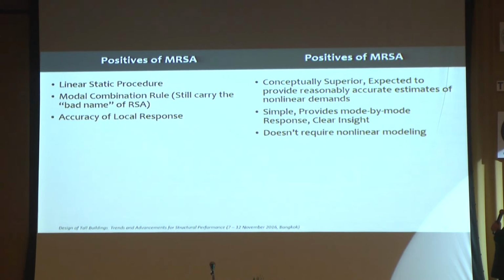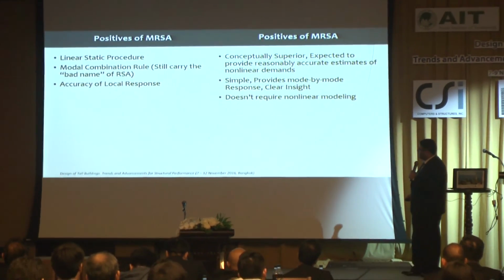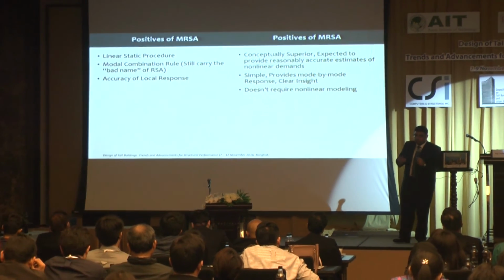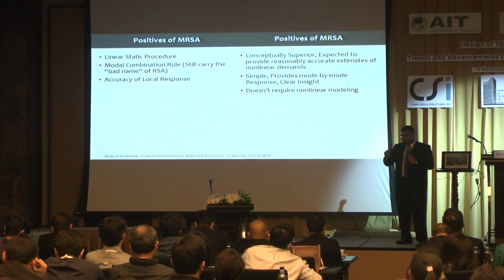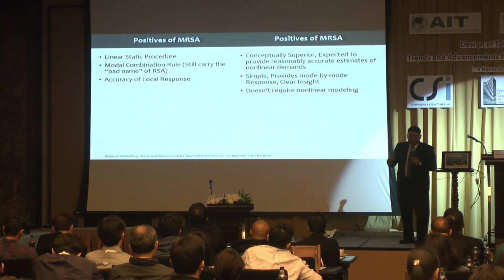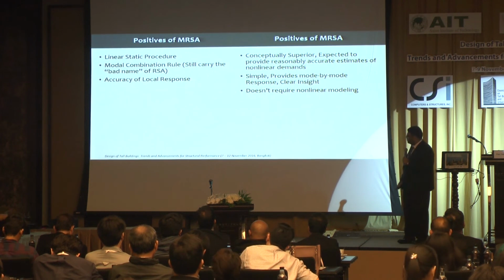So, that one should be negatives of MRSA, both cannot be positives. Sorry for that mistake. So, the negatives of MRSA is that it is a linear static procedure. So, all of the criticism which standard response spectrum analysis receives, this procedure will also receive. Except that we have found out a response modification approach which is more realistic, which can relate the modification amount to the actual nonlinear state of the structure. So no more R factor, we can just case by case, mode by mode, modify the results.